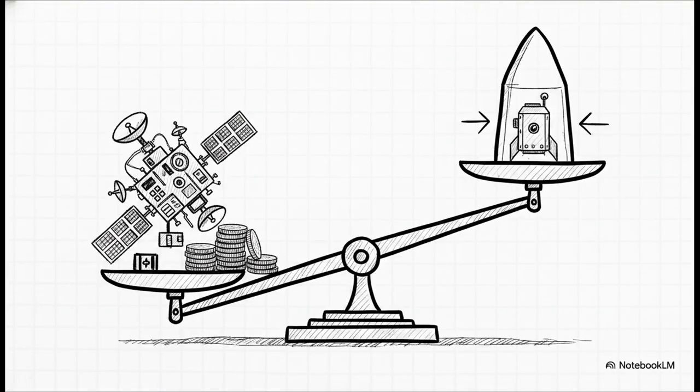Back to FireSat-2. This perfectly illustrates the classic cost versus performance trade-off. Say our first candidate sensor is amazing, but it spits out 10 megabits of data per second. To afford the giant transmitter needed for that, engineers might have to restrict the mission scope so the satellite only looks for flaming fires, not smoldering ones. Then, to save even more money, they might have to completely repackage the payload so it can hitch a ride on a less expensive Ariane rocket. It's a dance, right? The payload dictates the mission, but the budget dictates the payload.